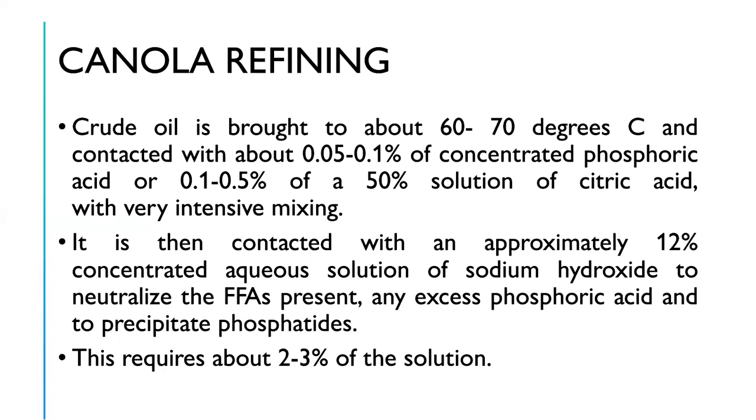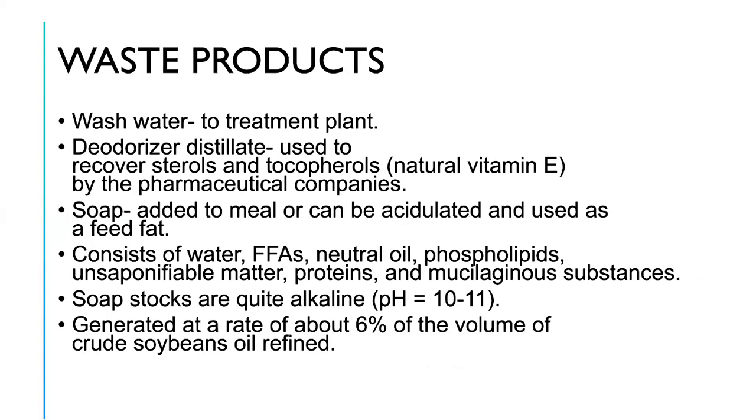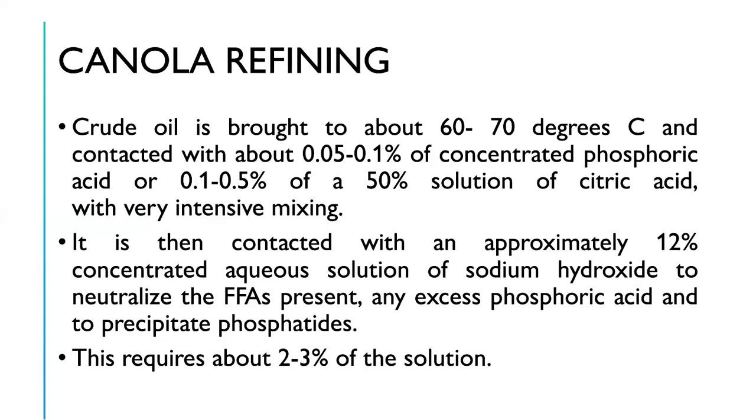So here we are combining the degumming and alkali refining, which means you first condition your oil by adding an acid, agitate for a certain period of time, then add your alkali solution, agitate for a certain period of time, then add hot water and let the mixture cycle for some time. Then you can separate your gums, you can separate also the water. You can also remove your soap, because those gums will be part of the soap now.